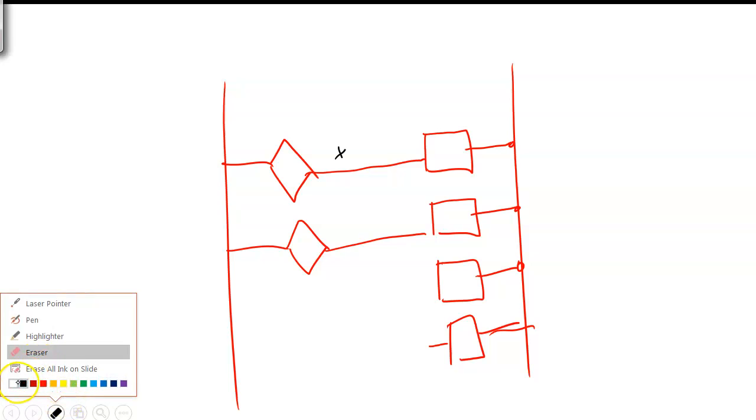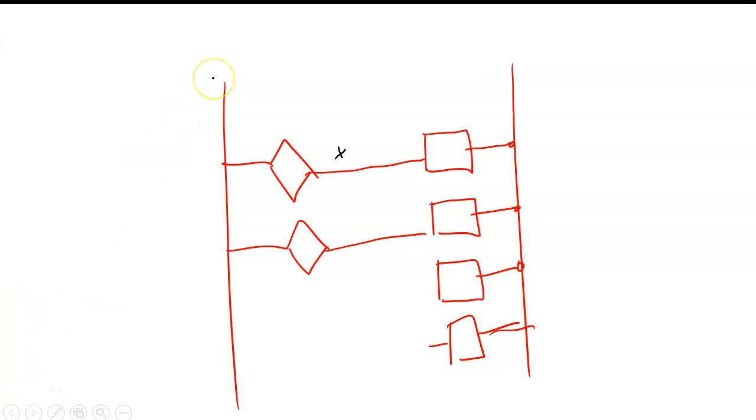I think I just said it wrong. So if this is a minus and this is a plus, then my sensor is going to give me a minus, if I said it right. That makes sense? Because we got to have what? So positive coming out of the sensor. Sourcing. Sinking. That's exactly right. And so over here, a PNP sensor is a sourcing sensor, and an NPN sensor is a sinking sensor.